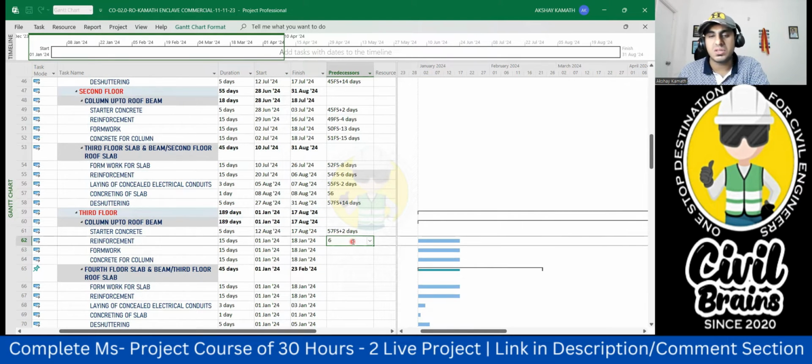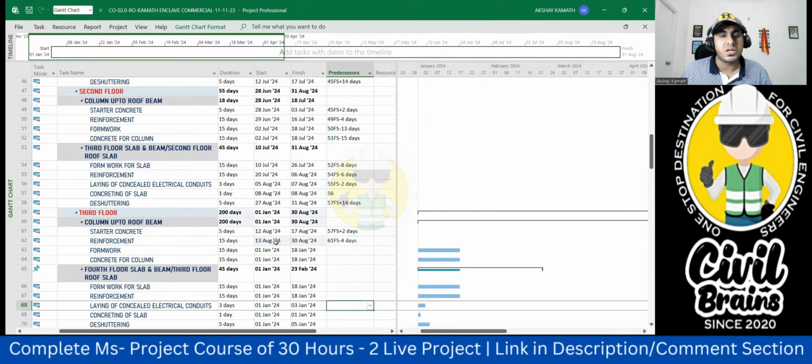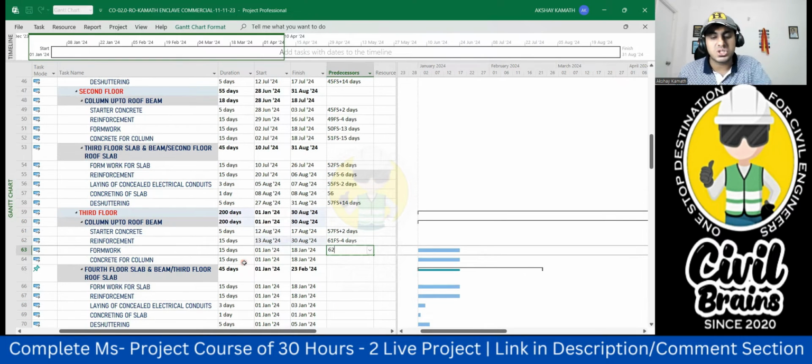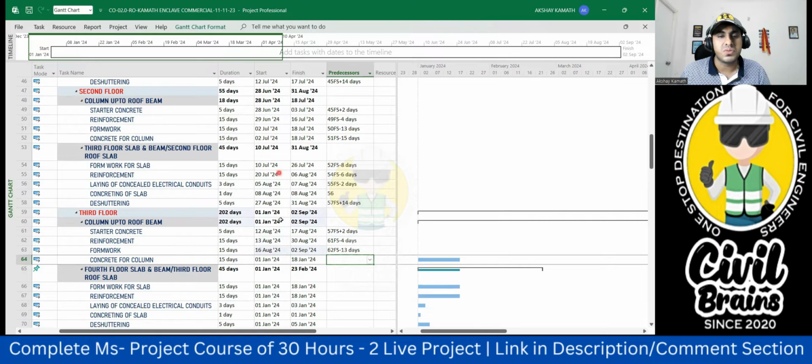Then reinforcement, what you will do? Reinforcement will be again 61, right? 61 FS minus how much will do? Minus 4 will do. 13th August will start, correct. One day lead you are taking. Okay. After that, formwork, what you will do? Formwork is 62 FS minus, tell me. So it will be minus 13 exactly. Minus 13. So 16 August will start, correct? No? 3 days gap from there. Where is your formwork? Yeah, 29, 3 days gap, correct.